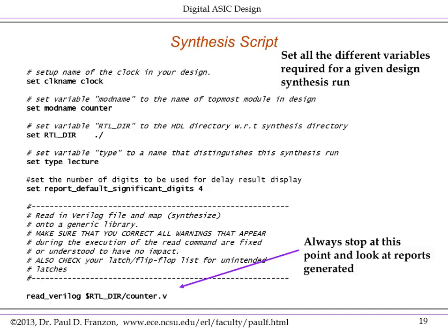The result of the read also gives you a list of all your latches and flip-flops. And it's important to check this for unintended latches. This is easy to do accidentally, to make unintentional latches. How that is done, we'll talk about in the next set of notes. So this is not meant to be a push-button process. You have to stop and look, particularly at this result, to make sure that you're going to get a good design.